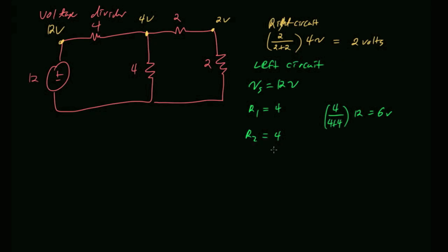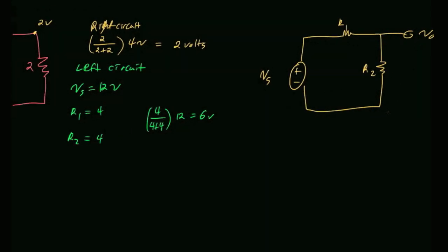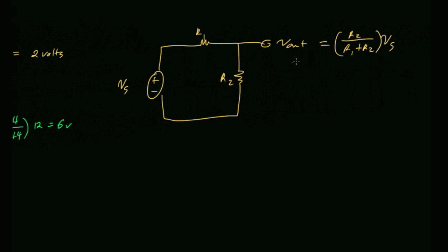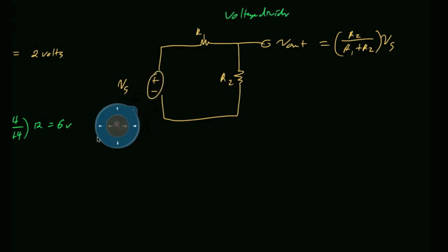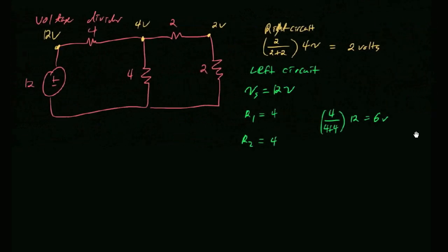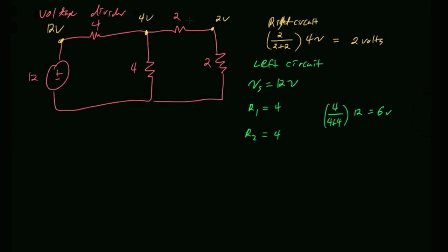First of all, do we see what the conflict is? I'm trying to paint a picture here. First we came along, we said, hey, voltage divider, look at this. If you remember this, it saves you a lot of time because then you don't have to do like 3 calculations every time. You just recognize it and do it once. So this is handy. And then I said, look, it's so handy that you can use it to solve this circuit. Right? You look at this circuit and you say, okay, 4 volts, 2 ohms. Oh, it worked out perfectly on the right-hand side. See how useful it is?